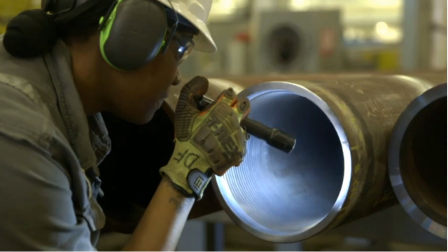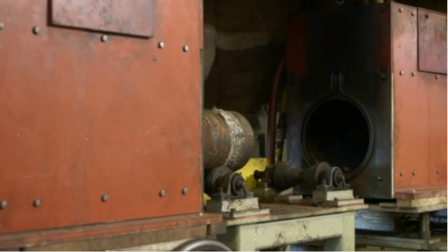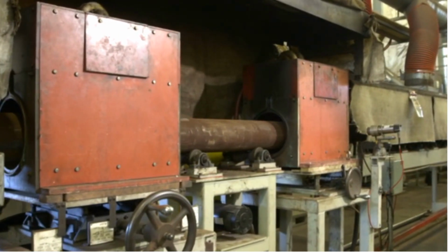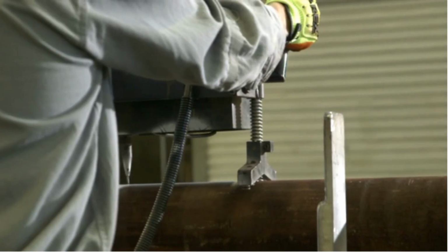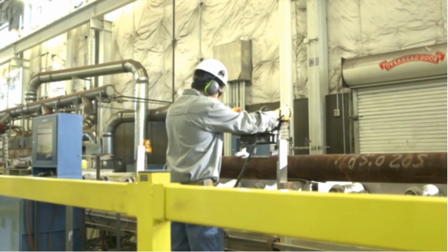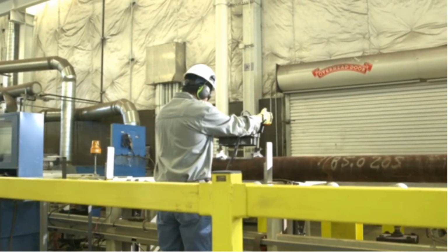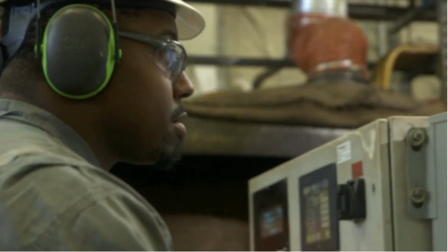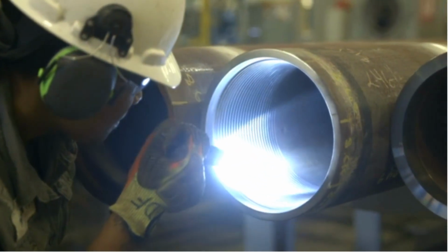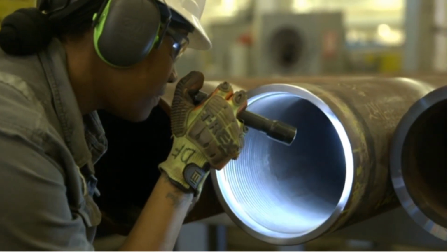Stators in need of relines are received in the facility and go to our CNC induction process to ensure all organic material is eliminated. The tubes are then transported by conveyor system to the stamping operation. There, each tube is identified with the internal tracking number and customer serial number for as-built records and full traceability control. We perform a receiving inspection to assess the incoming condition of the tubes and take critical measurements of the tube to get a precise fit for our mold tooling.